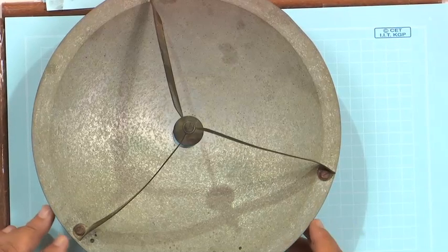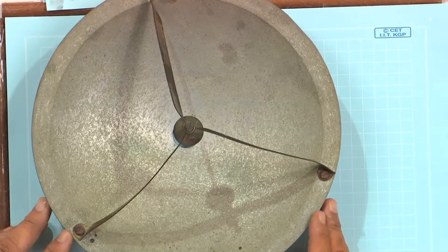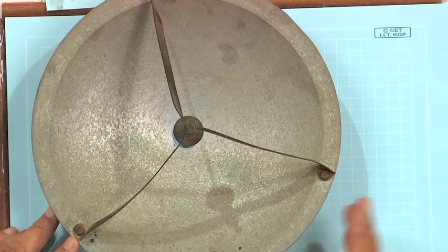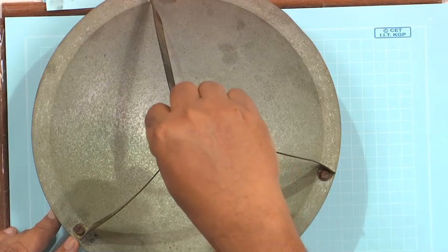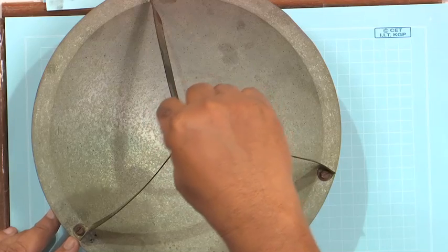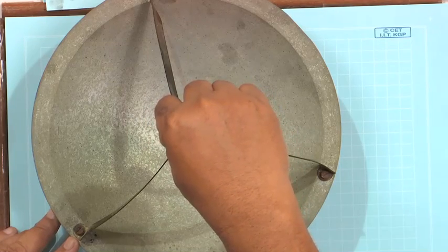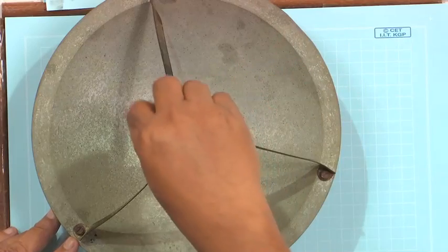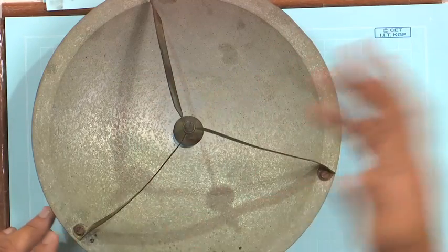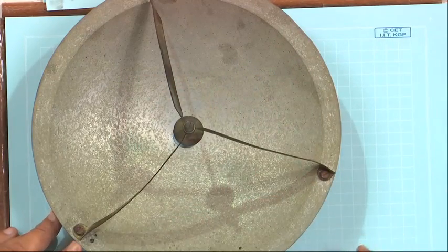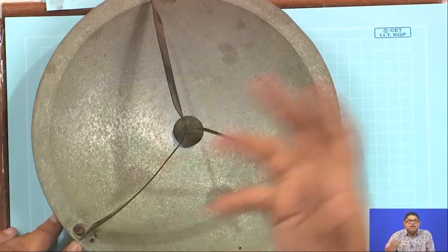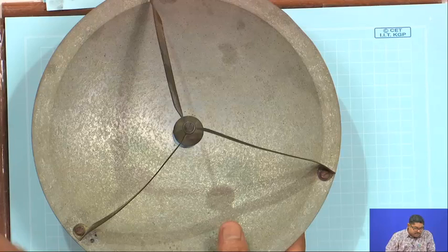This necessitates a long transmission line, which may give you significant loss. Sometimes the transmitter or receiver is directly put after this feed, but then the blockage again increases. Also, generally these reflector systems are put outside. So, putting a transmitter or receiver outside creates cooling problems and other problems also.